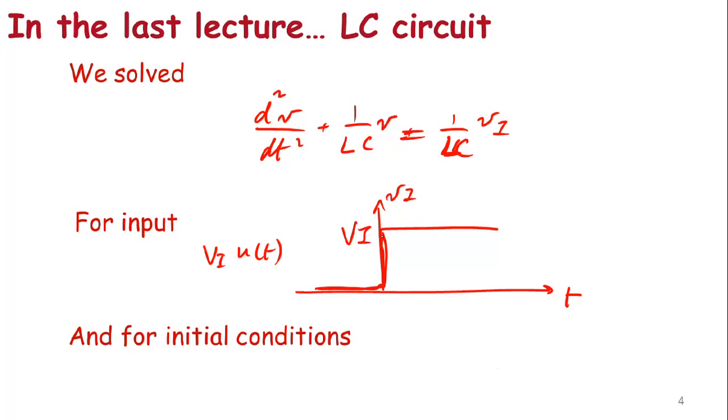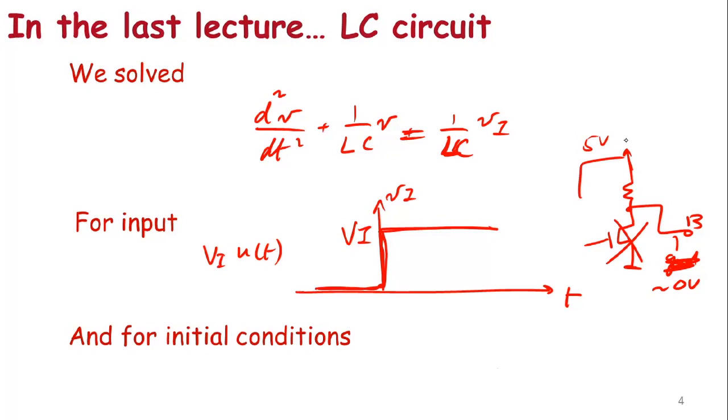Now the reason this input voltage, capital VI, reasonably modeled the behavior of the second order circuit was that, notice, when the MOSFET turned off, the MOSFET at the gate of inverter 1, so this was my MOSFET and this was node B. When this MOSFET turned off, and node B was close to 0 volts, and then suddenly, instead of having this input connected to ground, I turned the MOSFET off, it is as if 5 volts appeared at this node that caused node B